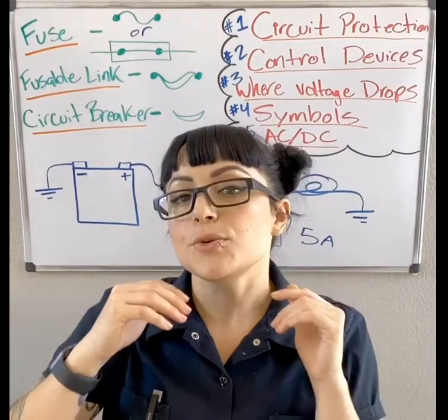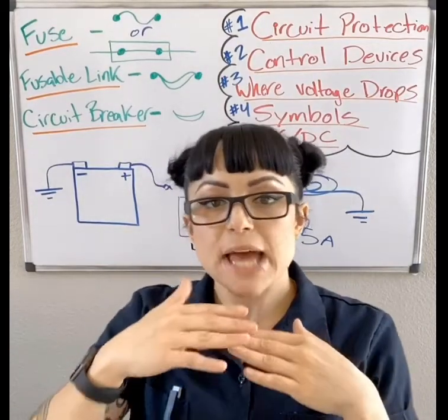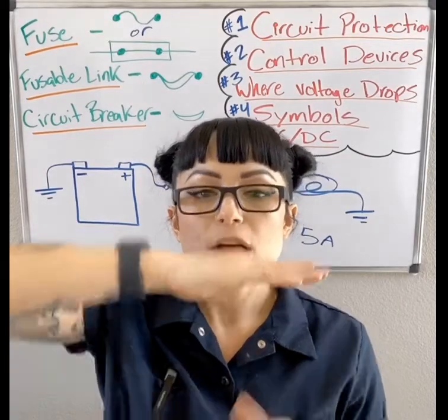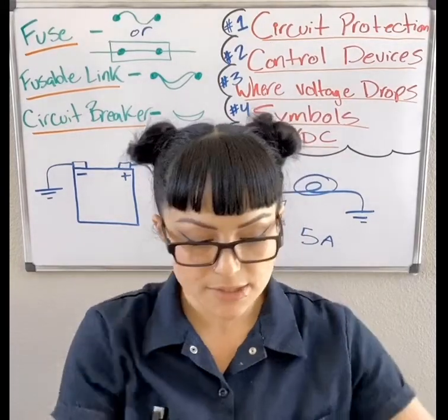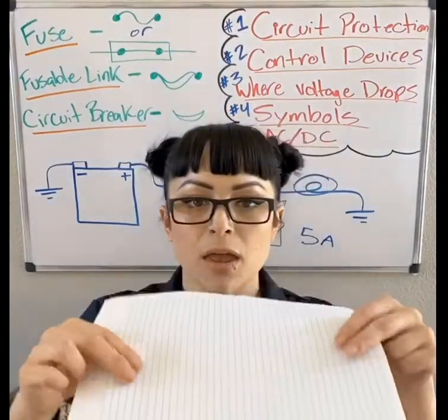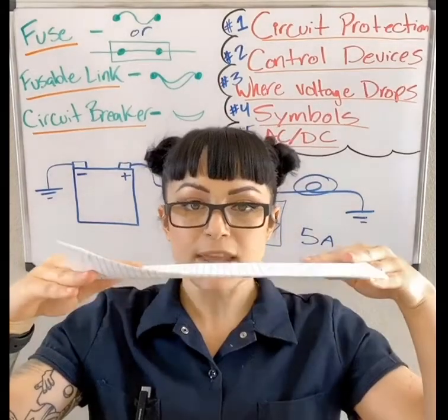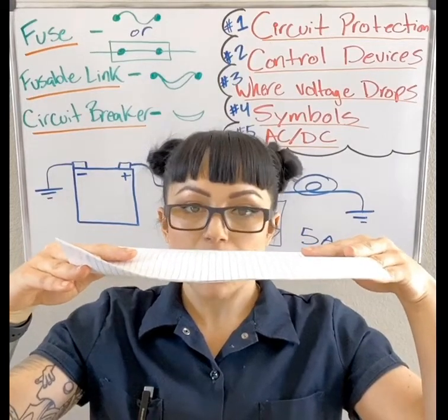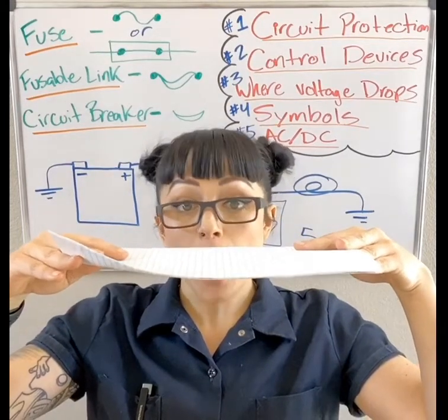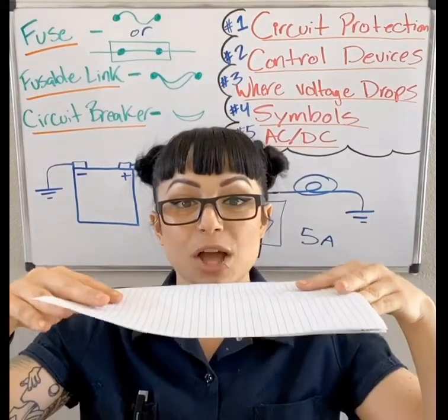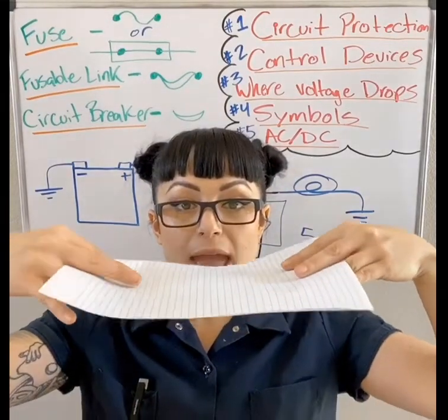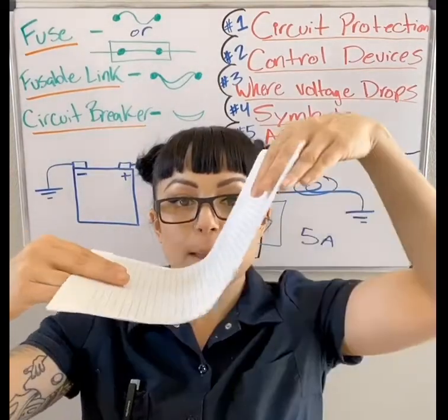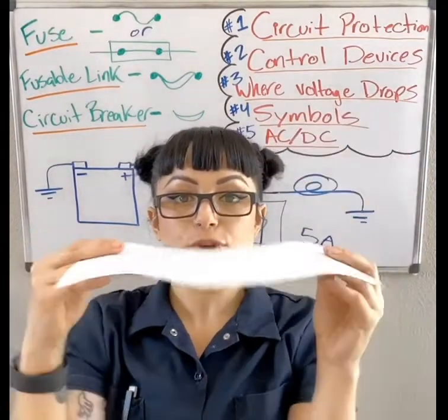Circuit breakers use a bimetallic strip or some sort of metallic strip that, once it reaches a particular temperature, will actually warp. So let's say this metallic strip was flat, making a connection between contacts. When it gets too hot because of too much current flow, we get this warping, and it will bend up and off the two contacts.